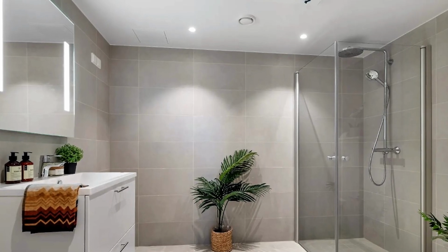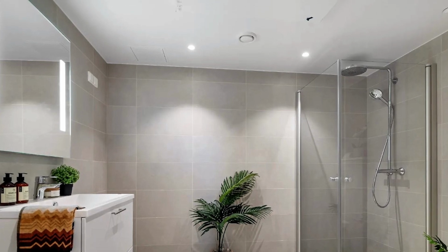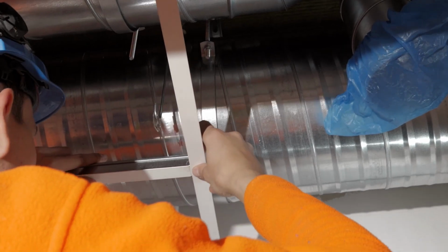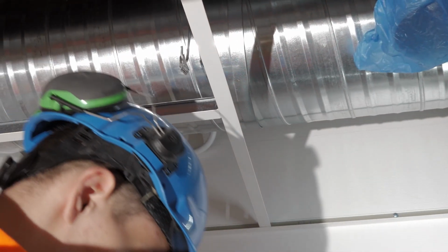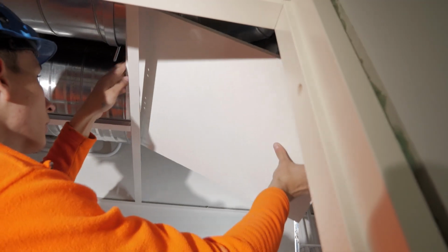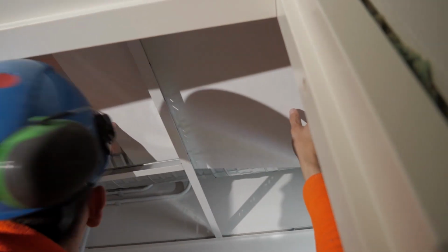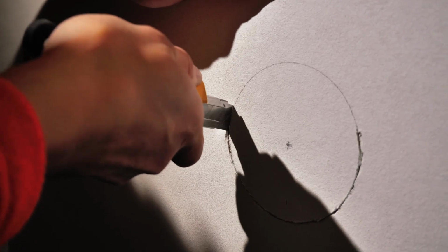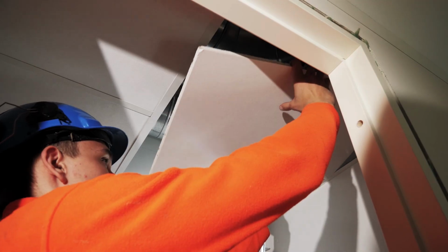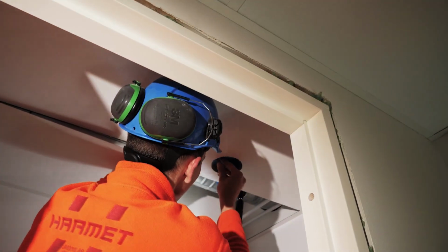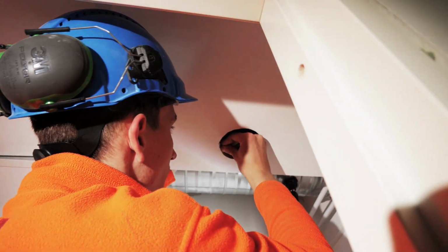Ceilings in wet rooms are often lower than the main ceiling and are made from gypsum boards, suspended ceiling tiles, or panels that have moisture-resistant properties. Suspended ceilings hide building services attached to the main ceiling, such as ventilation ducts, water pipes, and electrical cables. Spotlights and ventilation covers are integrated into the suspended ceiling tiles. For this purpose, holes are made in the tiles at the appropriate locations for the installation of spotlights or ventilation covers.